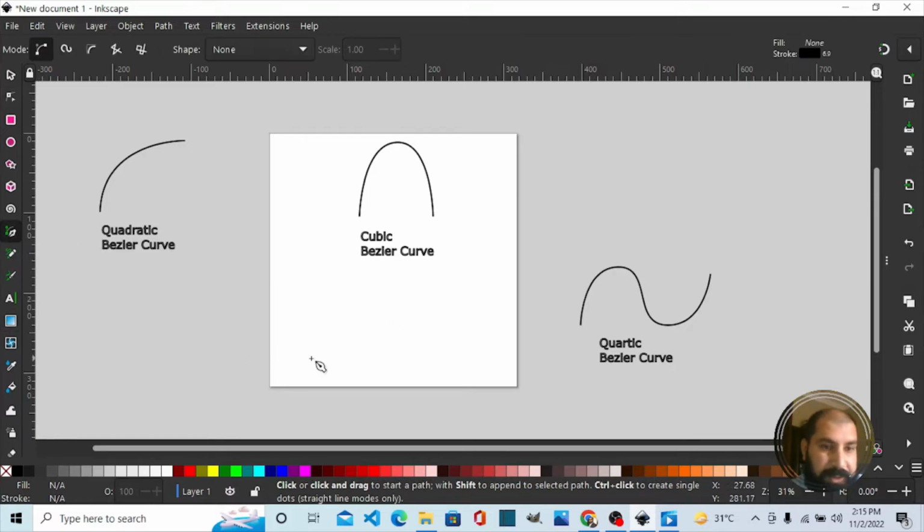I'm going to the Bézier curve, and here let me start with the click and a straight line, and here I want to draw the Bézier curve. So here I will press the left click of the mouse and will keep it clicked till I decide that this is the right curve. So let me click the left button of the mouse and keep it held. The two handles will emerge. Here we go, and as I move, the angles change with it.